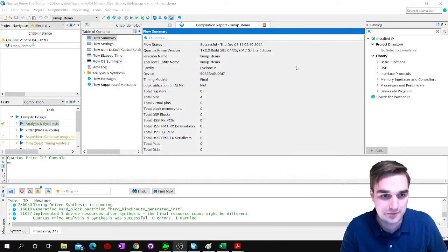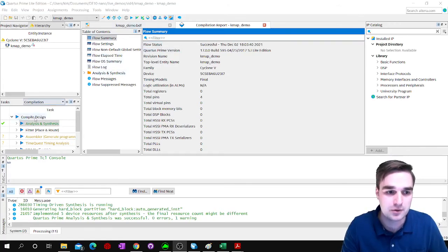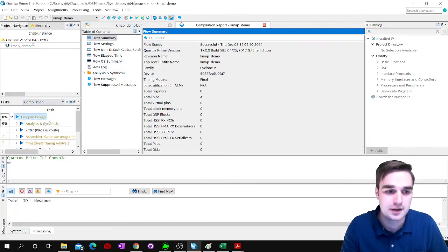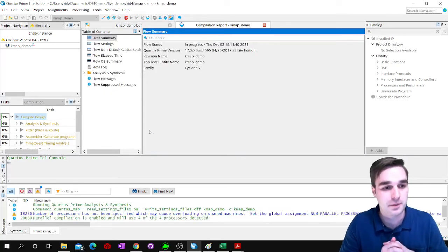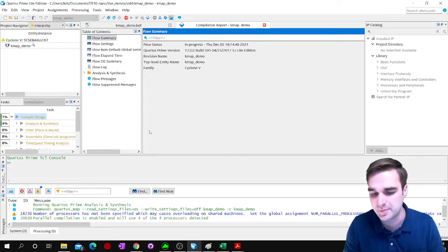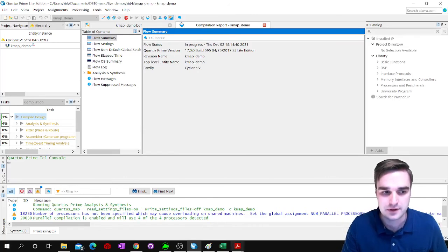Okay, so we'll close that waveform. We did our pin assignment. We did our waveform. We are ready to compile. So I'm going to right click on compile design, and I'll click start. This will take a moment, so I'm going to pause the video while this goes. It'll take a couple minutes, and we'll be back when this is done compiling.